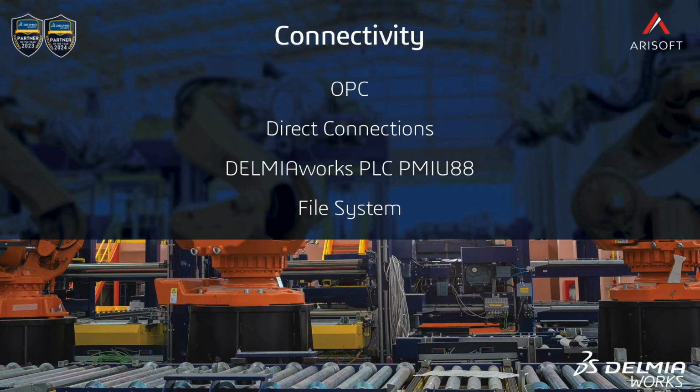KEPServerEX leverages OPC and IT-centric communication protocols such as SNMP, ODBC, and web services, and offers the broadest range of drivers available, supporting devices across various verticals within the industrial automation industry, and supports a variety of wired and wireless network mediums for Ethernet, serial, and proprietary networks. KEPServerEX supports the OPC Unified Architecture, OPC UA, specification, and many of the OPC Classic specifications, including OPC Data Access, OPC DA.